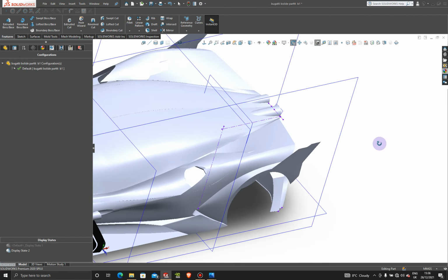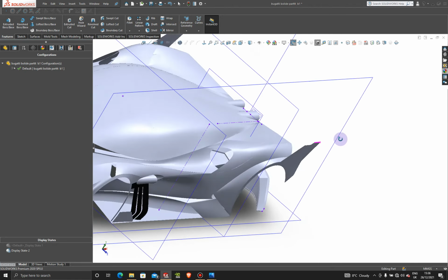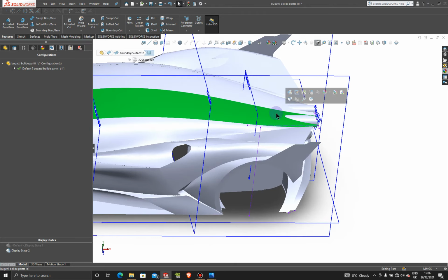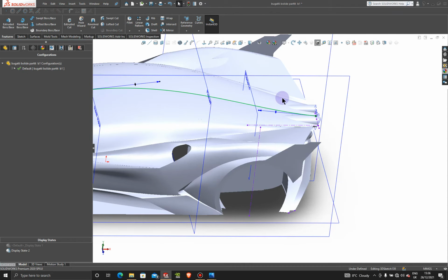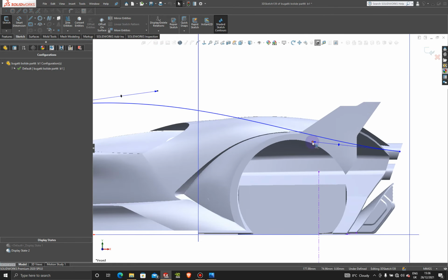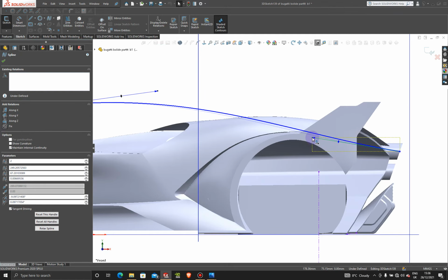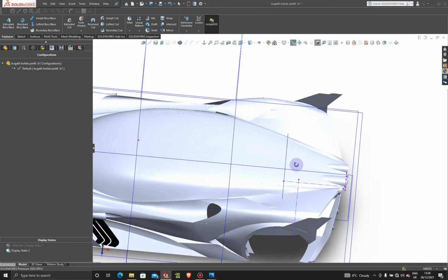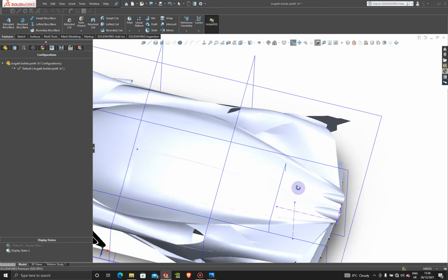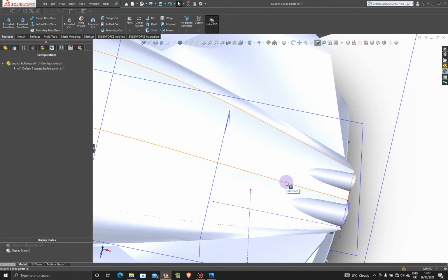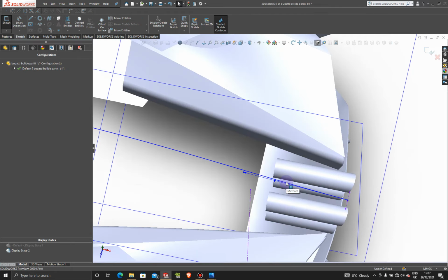However, to get rid of this dent, we can maybe move this sketch up a little bit. So let's click on this sketch and edit this middle sketch here, and get into the side view. We're just going to pull this up in this direction a little bit, and let's have a look. Alright, so straight away we can see that the bleeding amount is different on both ends, so that's not good. So let's do a Ctrl Z, and another Ctrl Z to get that line back down.